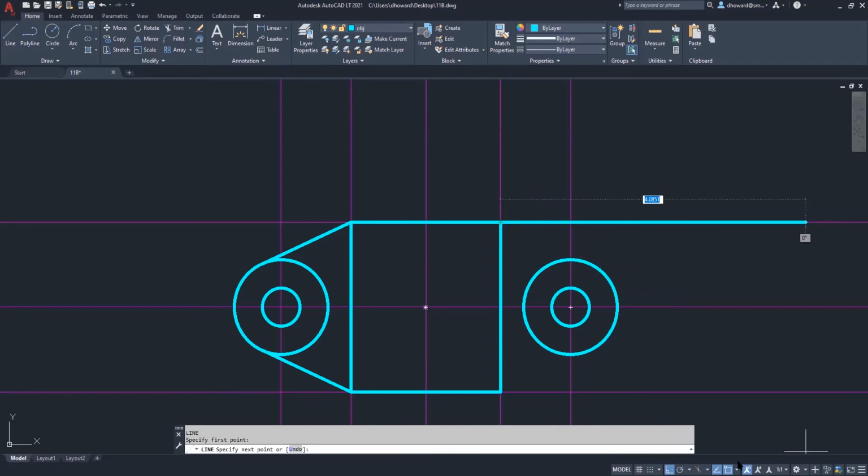And this, I'm telling you, it's probably a good idea to turn that nearest snap off. So I'm going over there, I'm turning it off. And now when I do my line, you can see the nearest snap's not popping up. It's just going for that tangent, and we're good. There, whoops. There it is. Okay.